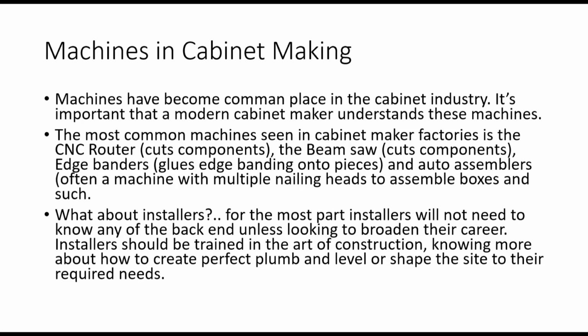If not a beam saw, then at least a bench saw, just for cutting straight, square components, multiple at once, so you can lay out 3 or 4 sheets at a time and cut multiple bases, multiple backs and everything like that. You can still keep up with a CNC router on bench saws and beam saws by just running multiple sheets at once.